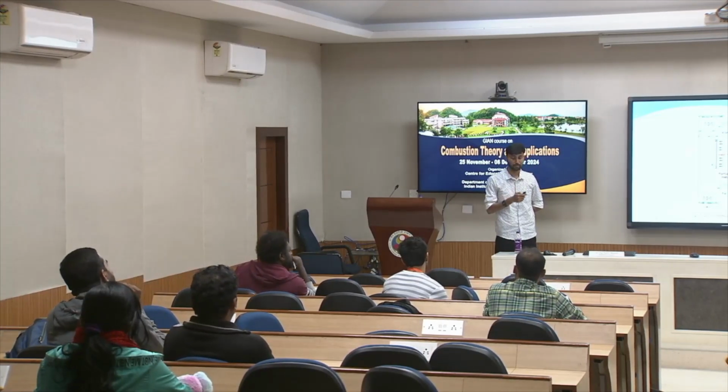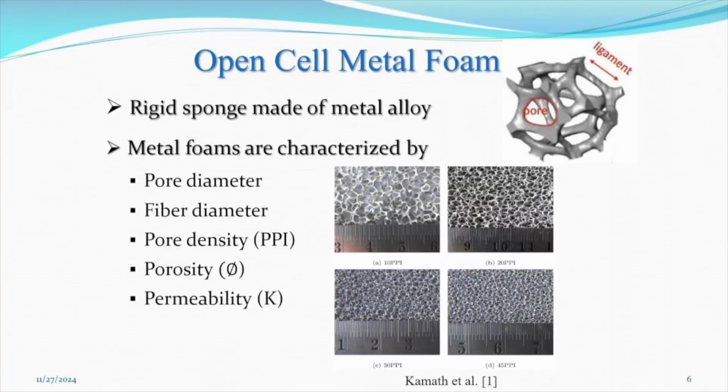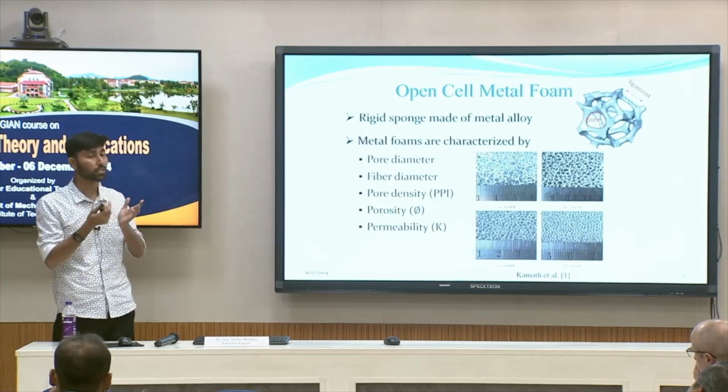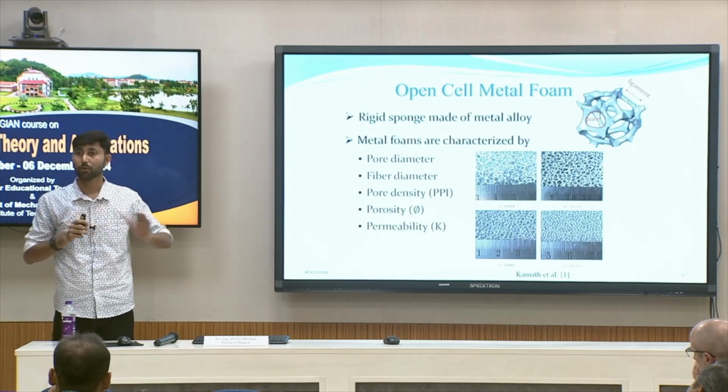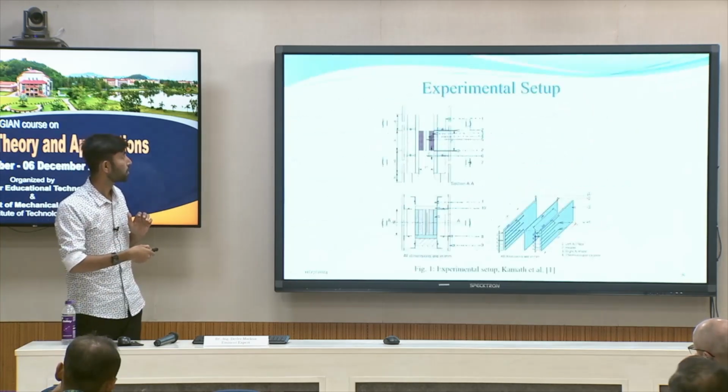Just go to the metal foam picture. It will blow from the bottom, so the holes will support the flow. That will allow the fluid to flow. But if you look crosswise, from the sideways, it will restrict the flow. Okay. So when there is no metal foam, fluid will easily flow, and in that case the heat transfer enhancement will be lesser. When we introduce this metal foam, we can see it here.